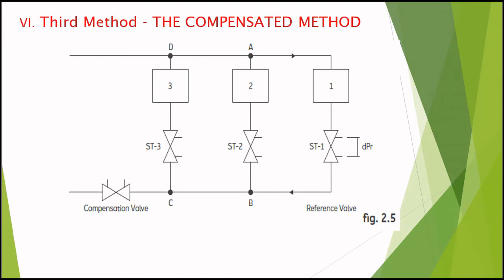Any disturbance on a branch causes, in fact, a general modification of the flow rate. This behavior of the hydronic circuits makes balancing difficult because after setting a single valve, any change that occurs on the following ones causes variation on the first and in turn in all the others.